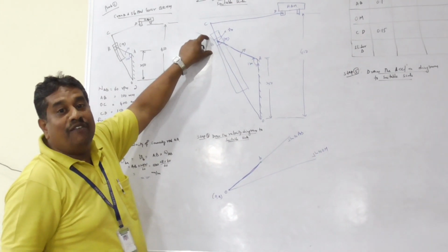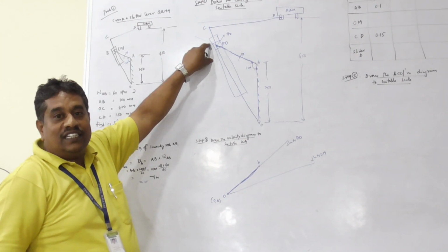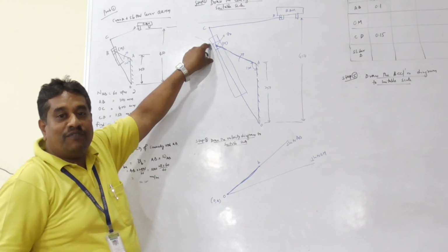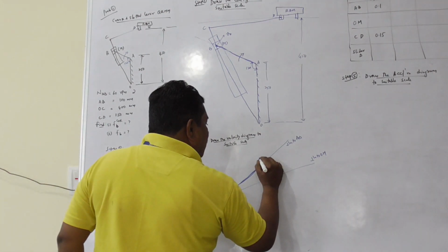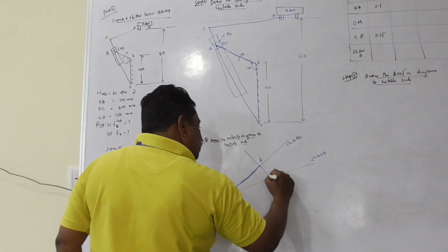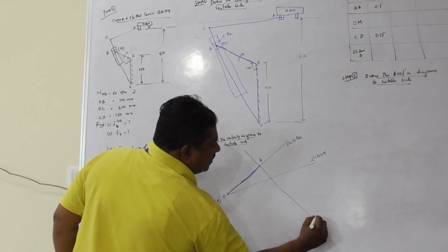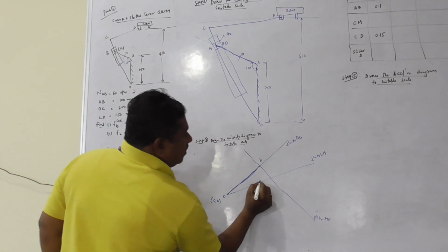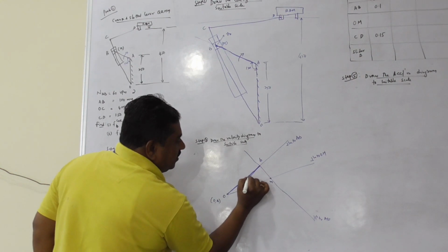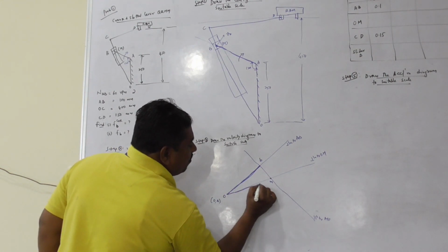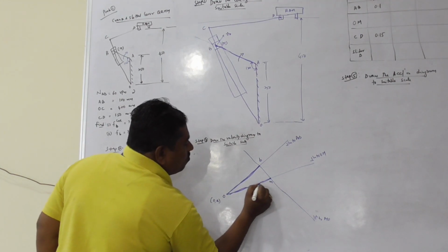Therefore, the moving point will have a sliding motion, sliding velocity. For all sliding members, the direction is parallel to the line of reciprocation. Therefore, through B, draw a line parallel to MO. This line parallel to MO intersects the perpendicular line at this point. Here I am going to get small m point. Therefore, vector OM represents the velocity image of the link MO.